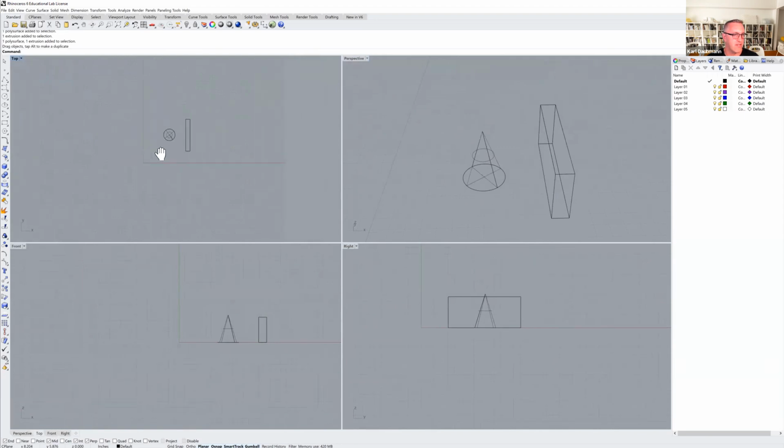And if you're in an orthogonal view and you hold down the right mouse button, it'll pan. And then the left mouse button, you can select the objects. The convention is that as it's selected, it turns yellow, which is also my caution: when you start using layers and layer colors, you don't use yellow as a layer color because you'll think those things are selected already.